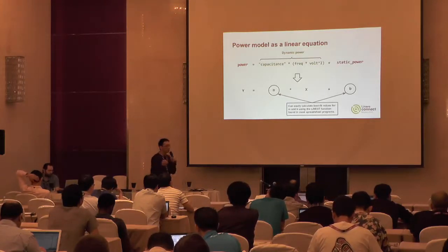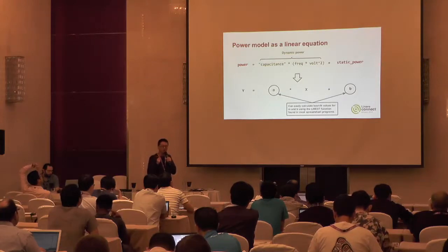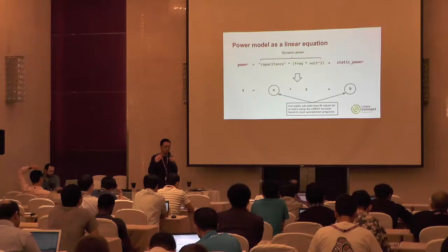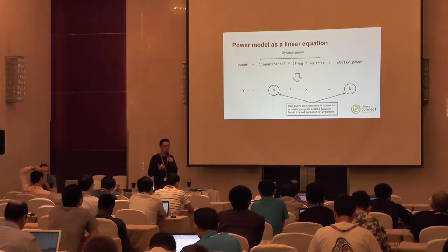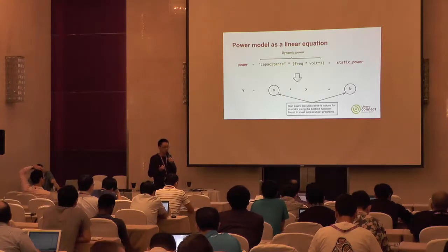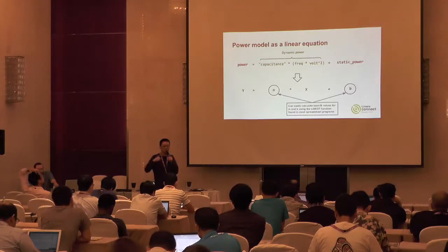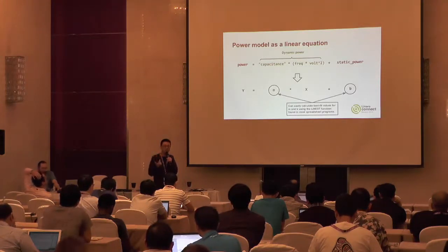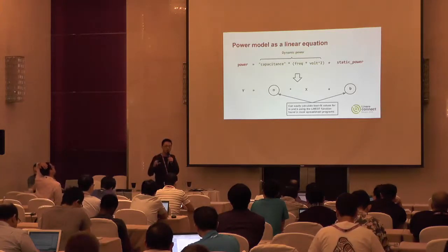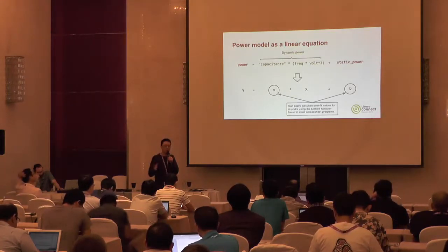But if we want to simplify this equation, I have some assumptions. The first is that we do well on temperature control for this SOC, for example, using the thermal governor, so the static power does not change too much. The second is that the static power is a small part of the total power data.